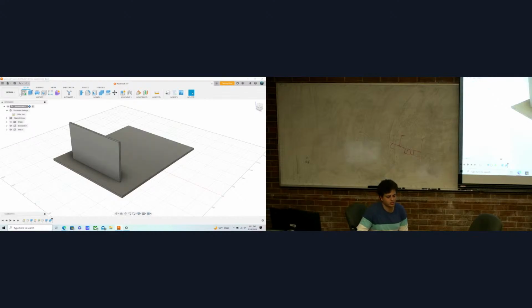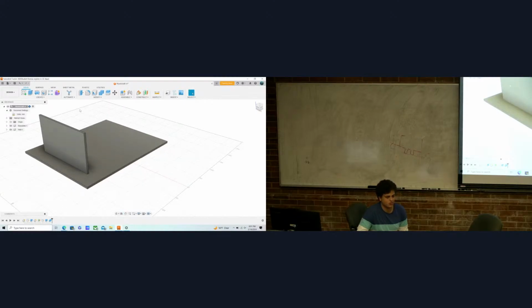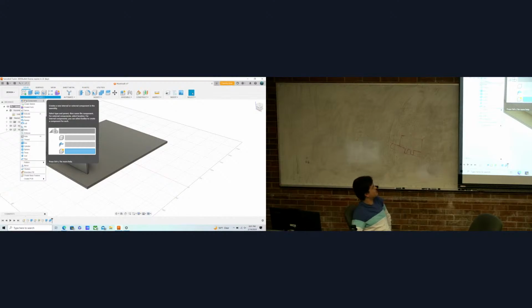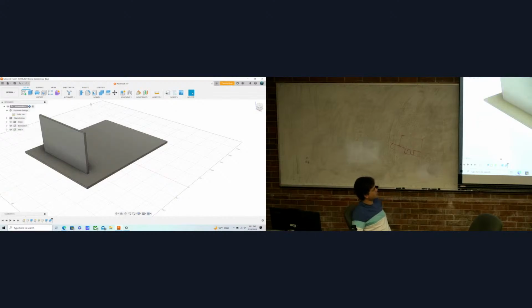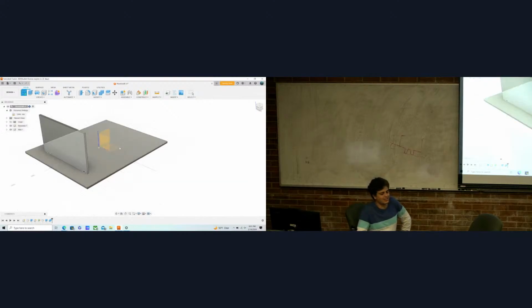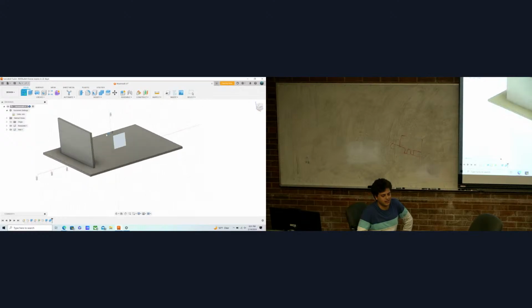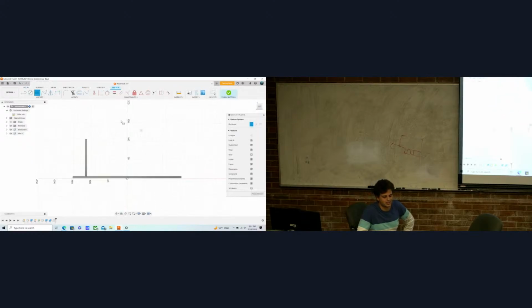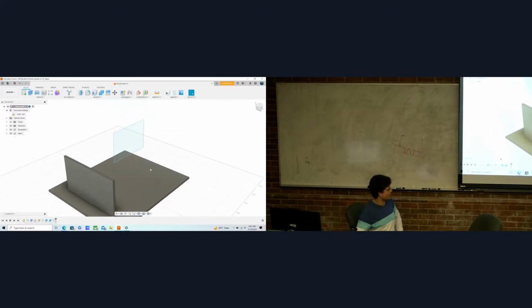One other thing I want to show you, which is not the way that we made this: we were explicitly making new components like this. There is kind of a shortcut, but you want to be careful with it, because if you don't do it when you make it, you can't do it later. Let's say I am making a square here. I'm going to press finish even though I'm not constrained, just for example purposes. Don't actually ever do that. Make sure you constrain things.